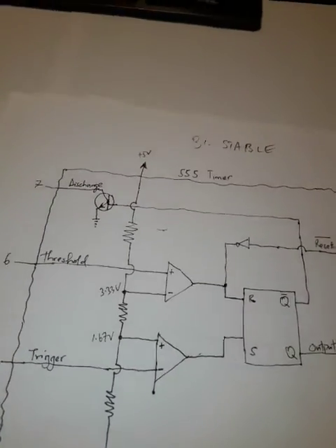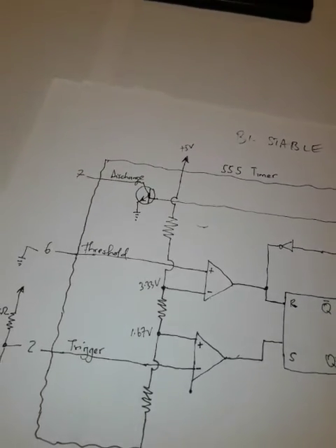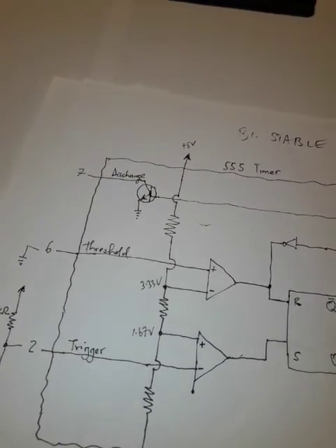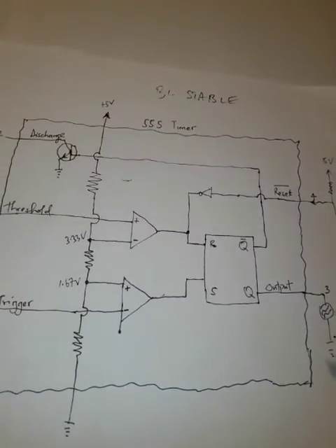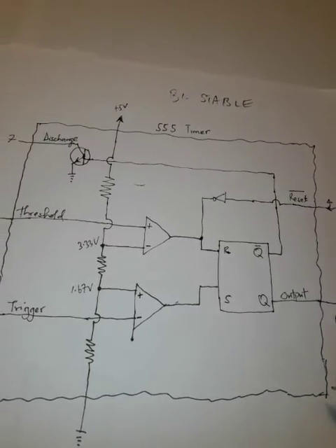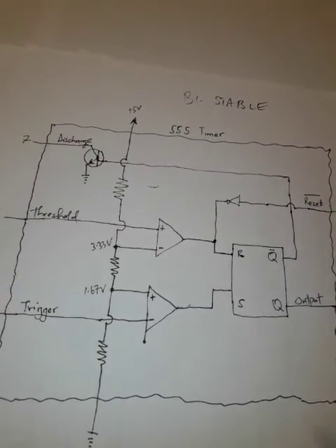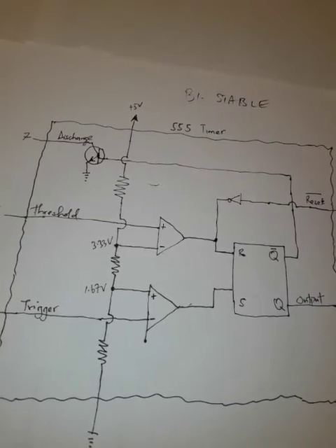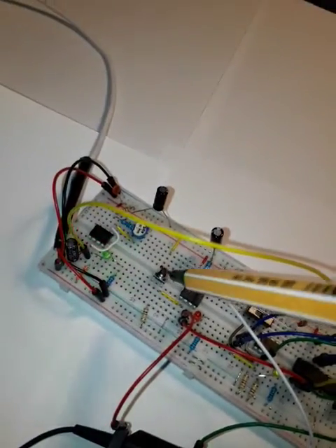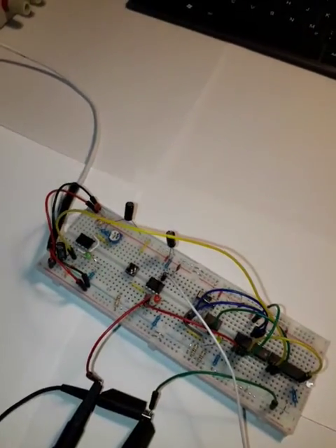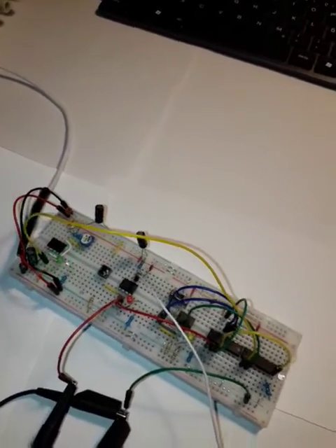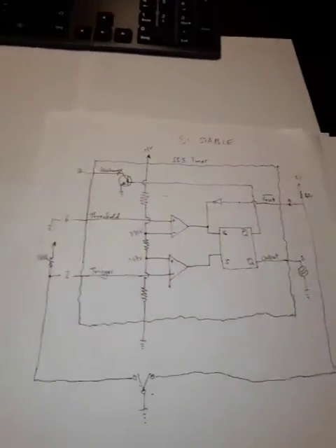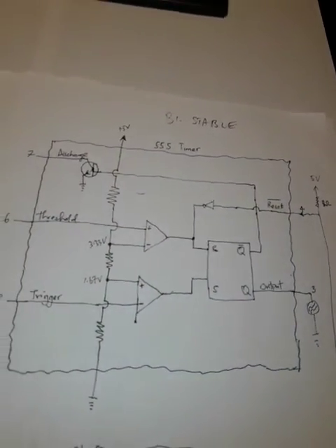And yeah, the reason is because we're going to be using this clock system for a computer, and when you want to debug the computer or perform a debugging process, you just want to have one pulse at a time each time you're stepping through your program. And this means, because we're using these switches, they have a lot of bounce when you hit it. So in order to be sure that you have only one pulse each time you press the button, we can use this kind of mode to produce that.